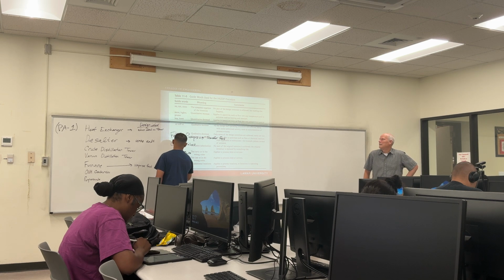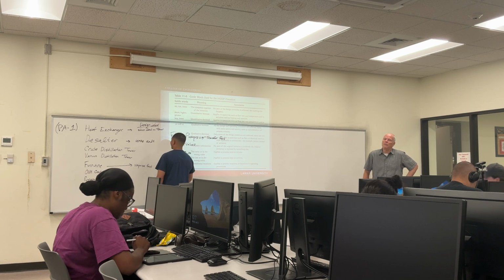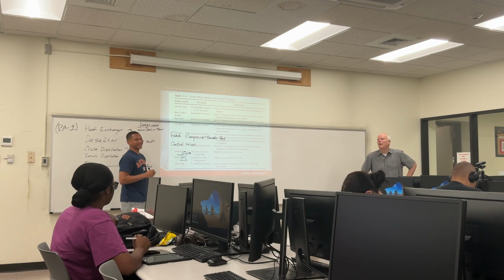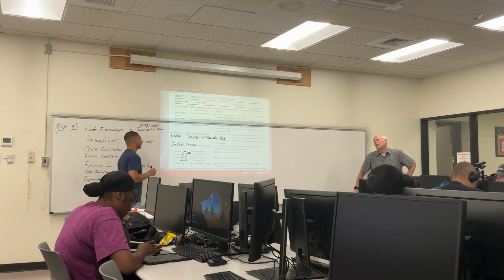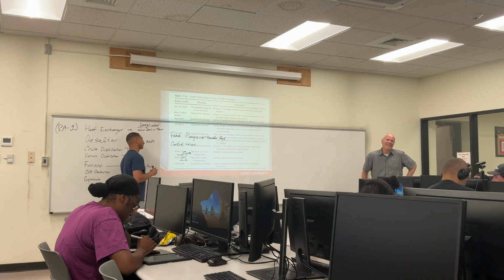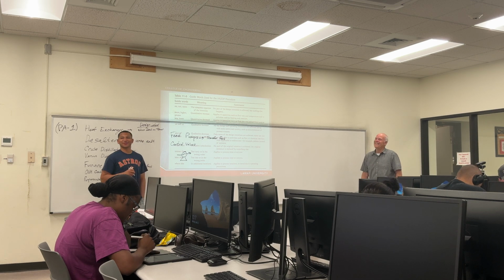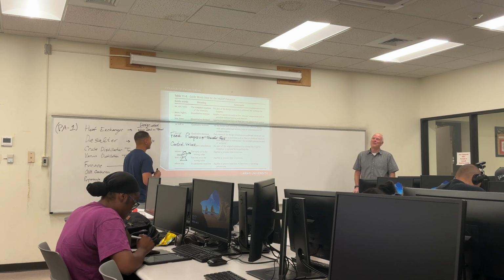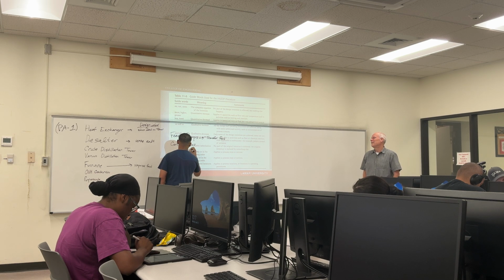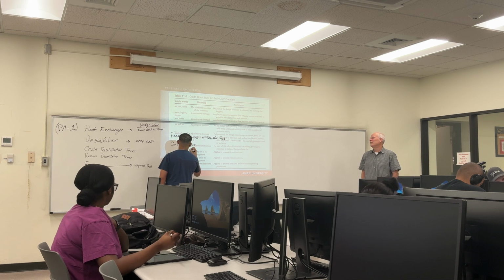Somebody help them out, where are we going to put a control valve? Oh my gosh, is this a control problem? Is anybody in here taking control? No, I'm not taking control. Restrict flow. Anybody want to help me? Where are you going to put the pump? I see them sitting there on the entrance of the pump, but that is not where you want to put a control valve. Put the control valve on the outlet of the pump, please. You know what a control valve looks like, right?